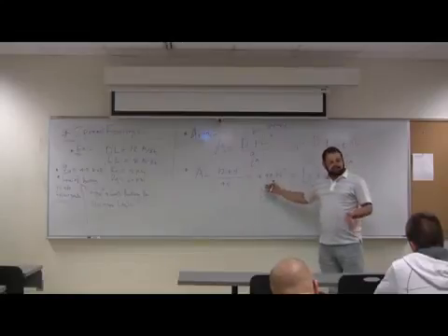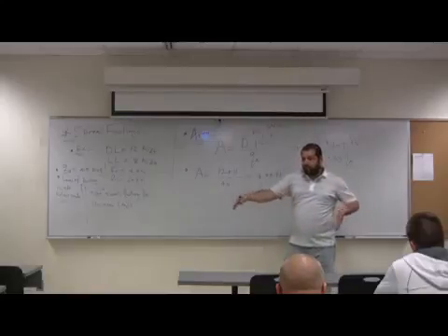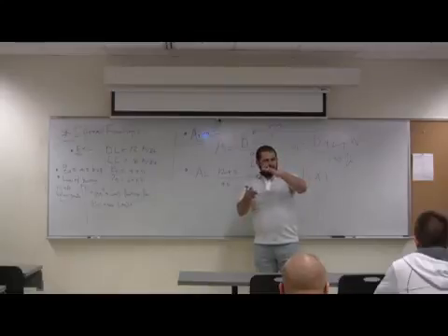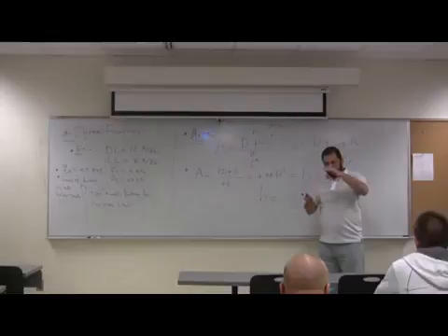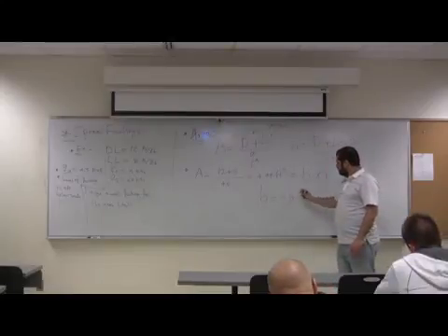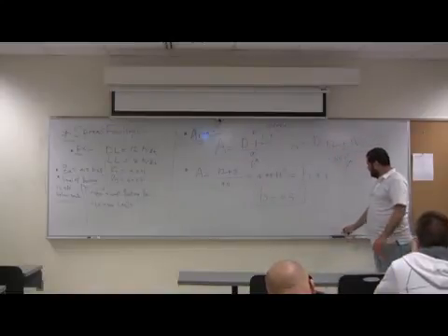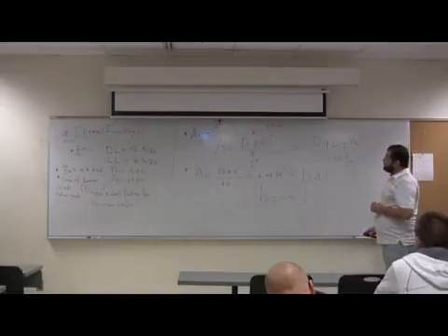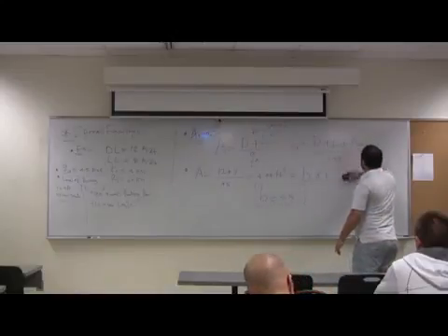You want to go with 5, that's fine too. If you increase the width, if you have room on both sides to increase, you will require less reinforcement. Okay? But we're going to use 4.5 foot. So that's the first item. Okay? So we have B.